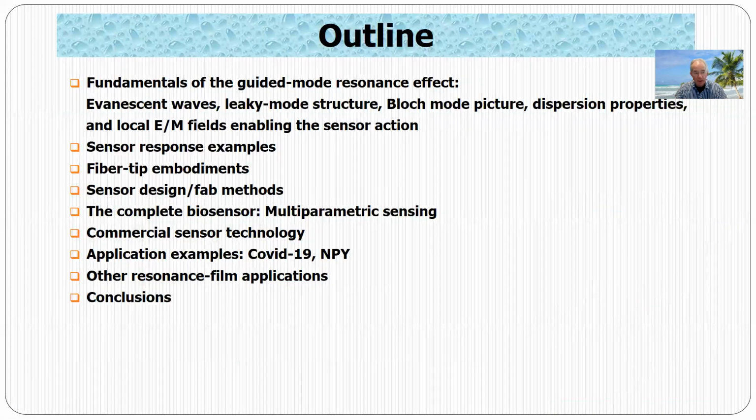Here is the outline of my talk. I will begin with the fundamentals of the guided mode resonance effect. This includes evanescent waves, leaky mode structure, the Bloch mode picture, their dispersion properties, and the local electromagnetic fields that enable the sensor action. I will show some sensor response examples, fiber tip sensor embodiments, and discuss fabrication and design methods.